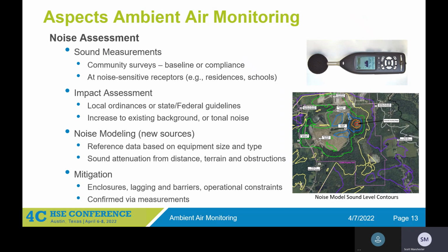Sometimes it's a matter of operating the equipment at different times. Daytime's better than nighttime, with higher background sound levels, or it could be operating at a different speed. Sometimes certain speeds are problematic and make more noise than other speeds. There's also different types of equipment that are low noise. A lot of equipment that makes a significant amount of noise has low noise packages or low noise equipment that can be spec'd instead of the regular equipment, and they're effective in mitigating noise, like a low noise generator.